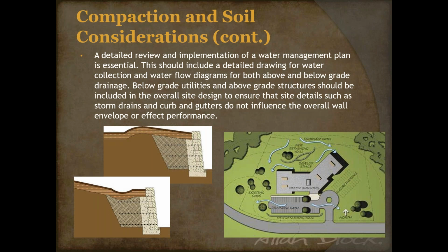It should be up to the engineer to design the site so that water is handled in that regard, whether that be with swales above the wall or just grading the site so that the water doesn't make it to the wall. And on the left there, you can see a couple images. There's a swale in one of them, and there's sort of a berm in the other one, which might handle some of the water at grade pretty well, but along with that, the water behind the retaining wall, because it's undoubtedly going to get in, at least some water, needs to be designed to be routed out.